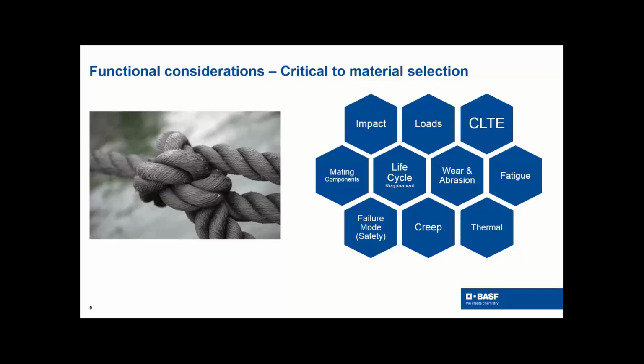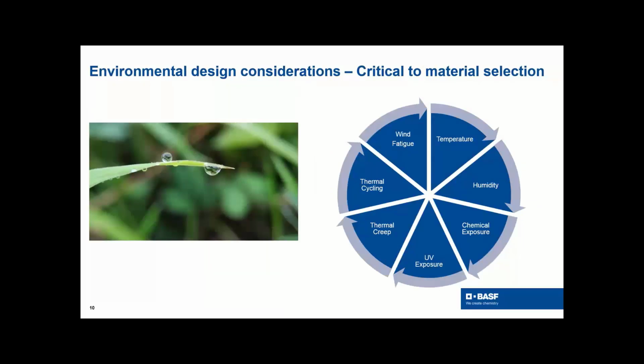So you have your application that you're thinking about designing in plastic. So first thing to do is what I like to do is to pick 3 most important requirements of your application. So is it impact? Is it thermal? It's going to see high temperatures. Is it fatigue? Whichever, and again, I pick 3. In some applications, it's more, but the top 3 are probably the most important. And in some cases, it's only 1 or 2. But I guess the point is to know what is important for your particular application.